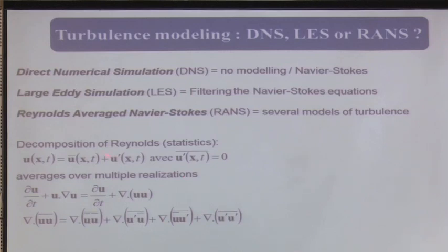And then the job is to evaluate, to calculate what are the equations for the evolution of the mean. Not the equation for the flow field, because we know that the equations are the Navier-Stokes equations. So the question is, if I take the Navier-Stokes equation, what would be the modifications of these equations to predict the mean, instead of the instantaneous flow field.